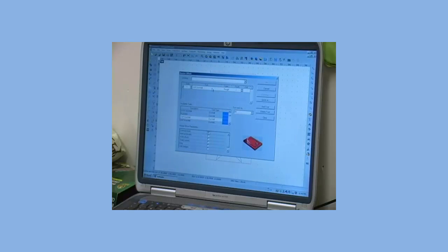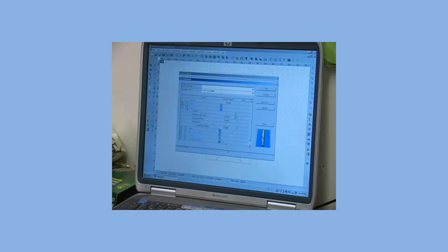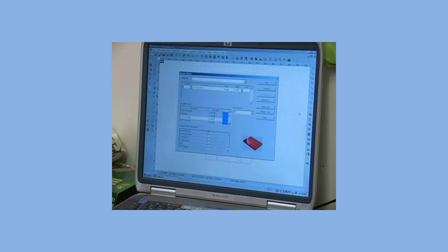Select 0.18 for your depth. Go to Edit, make sure passes is 1. OK. It will tell you that you're going deeper into the wood. Now, very important, we come down here to the bottom. External male is checked. However, we want female parts now. Go internal female. And also check inlay and leave it at 0 tolerance for the inlay gap. Go ahead and hit OK now for your toolpath.